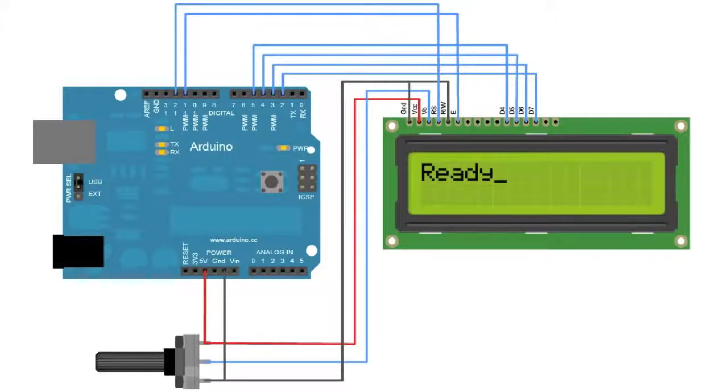This is because we're going to operate the LCD in something called 4-bit mode. This is when instead of sending the 8-bit character command value in one go, we send it in 2 half bytes or nibbles in a row. This just saves I/O pins. Also, the potentiometer is about 10 kilo ohms and it adjusts the contrast of the display like this.